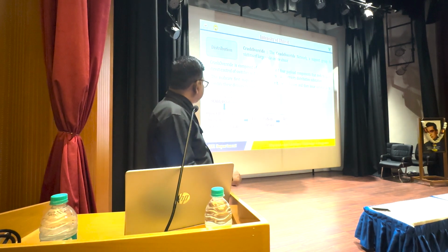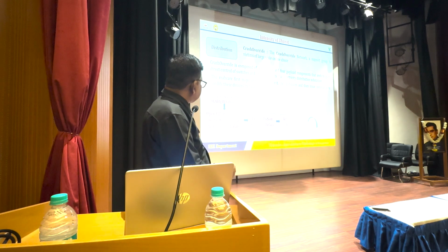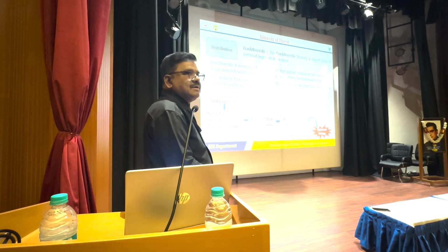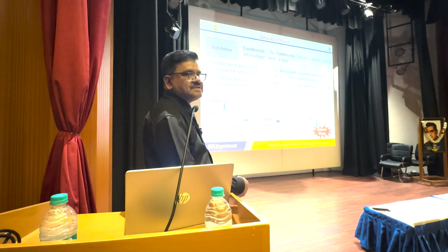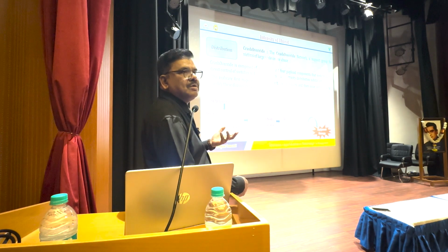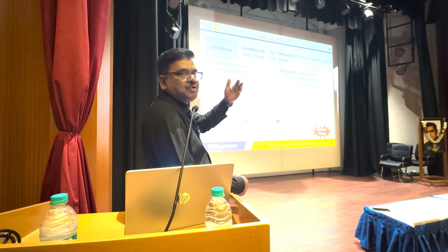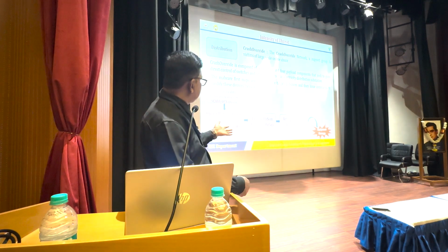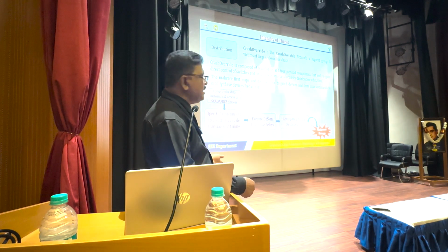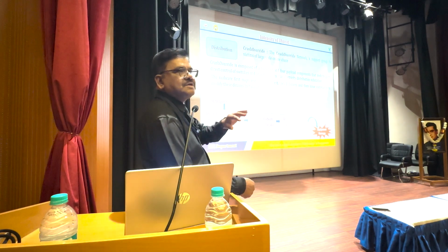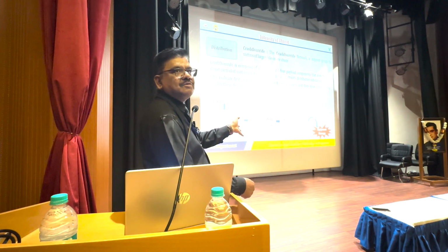So what happens at this stage? Whenever this DOS execution happens, your load is disconnected from the generator. The generator will be rotating without load, so generation continuously increases, and nobody is there to consume because of this attack. Suddenly you close the circuit breaker, so again a physical interconnection happens, and the load is suddenly connected onto the generator.